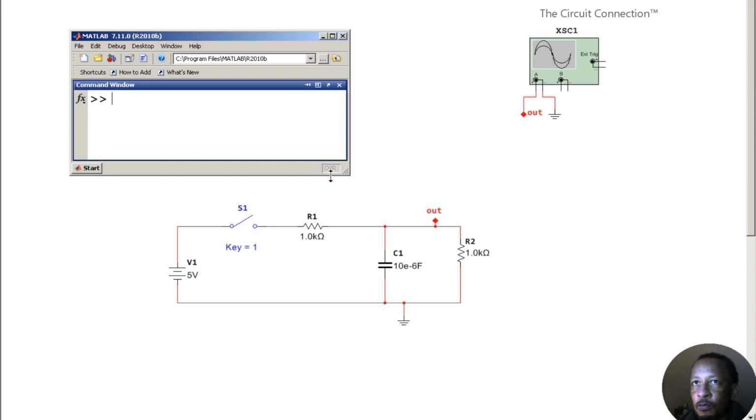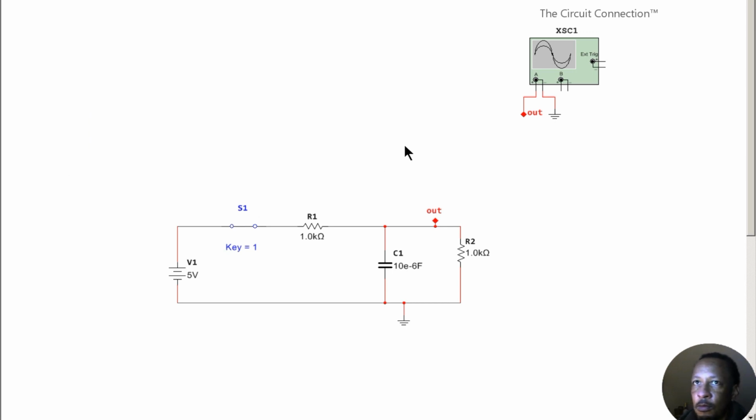For this circuit here, when I close the switch, I'm going to have both R1 and R2 included in the circuit. So how do I come up with a figure for the net resistance? Well, if you just reorder this circuit a little bit, just to see the net effect on C1, you see that of course you have this voltage divider, so all C1 is going to be subjected to in its voltage divider configuration is the open circuit voltage, and that open circuit voltage is the voltage divider amount coming from this node here, right?